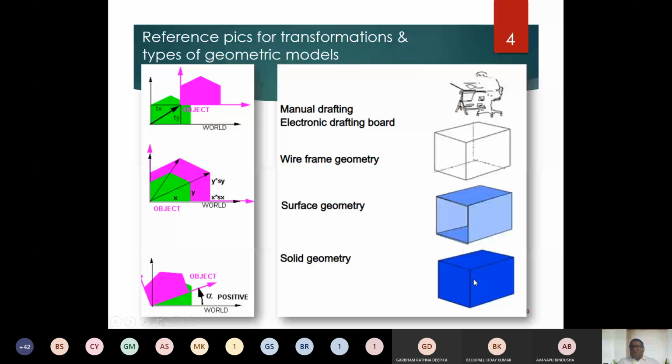So in the second unit, you are going to talk about different types of curve entities and the mathematics behind the curve entities. And there is something called synthetic curves also. They are also part of the second unit, synthetic curves. But synthetic curves are an evolution of analytical curves. Evolution means, for example, spline curve. We already know about a spline, how to create a spline and all. So simply by picking a few points, the spline would be created in AutoCAD, right? So they are all a kind of synthetic curves. So we also talk about the mathematics behind the synthetic curves as well in the second unit.